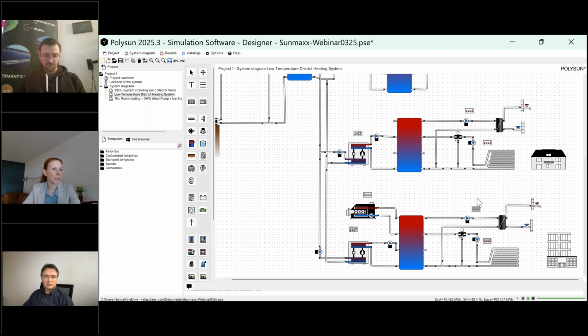So you can see that we can also take into account all the specialties that this district heating might need. It can be a single decentralized heat pump that supplies these retail buildings with a combined storage, because we have little need for domestic hot water, but a lot of space heating, for instance.